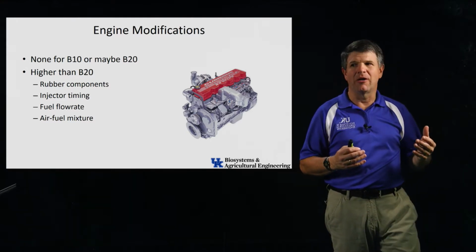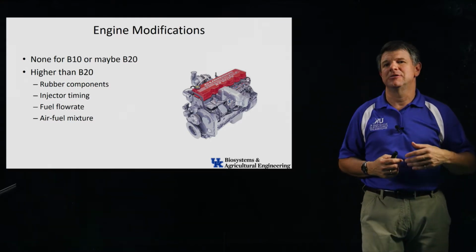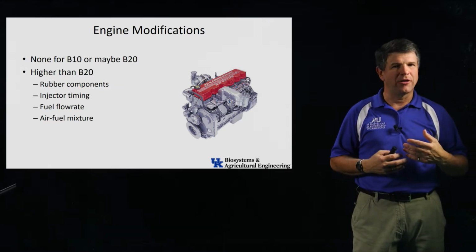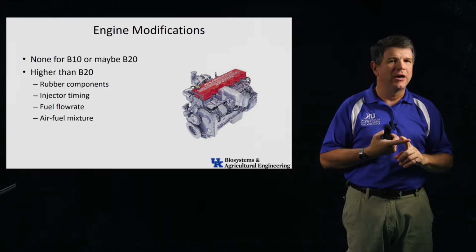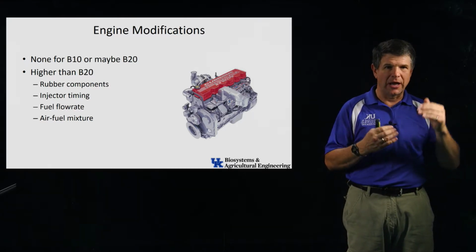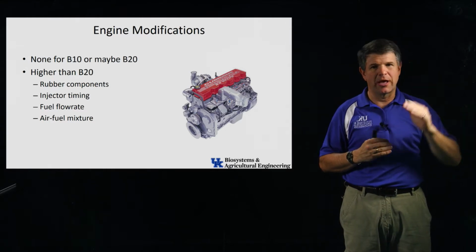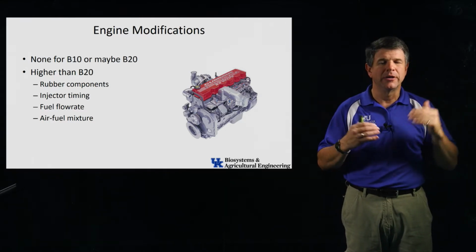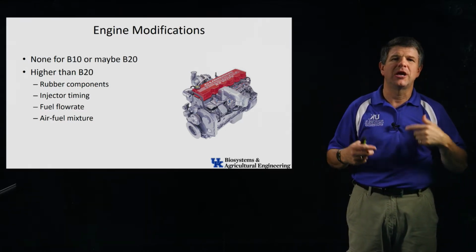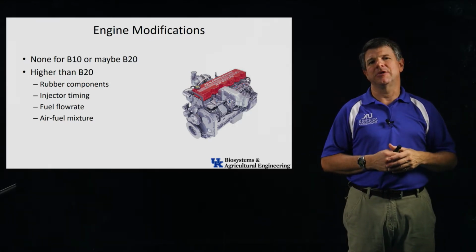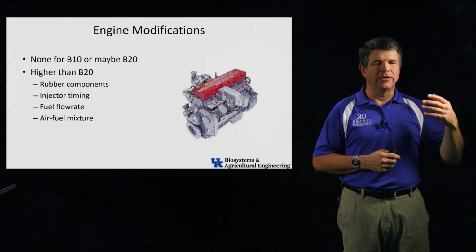I've kind of hit it all the way through this, that most of our modern engines have a lot of pretty sophisticated electronic controls in them, so they can do a lot of things. They can change the timing of the injections or the spark. They can actually change the opening of the exhaust and the intake valves, when they open, how much they open, how long they stay open, and so forth. So they can change all that dynamically. They're doing a lot of things within the engine to compensate for different amounts of fuels, different atmospheres.